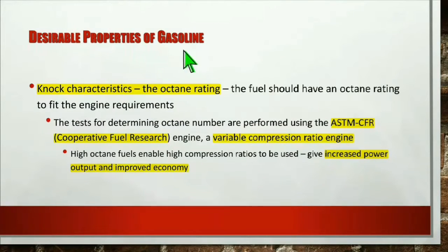Desirable properties of gasoline. ON characteristics. The octane rating. The fuel should have an octane rating to fit the engine requirements. The tests for determining octane number are performed using the ASTM CFR, Cooperative Fuel Research engine, a variable compression ratio engine. High octane fuels enable high compression ratios to be used, give increased power output and improved economy.